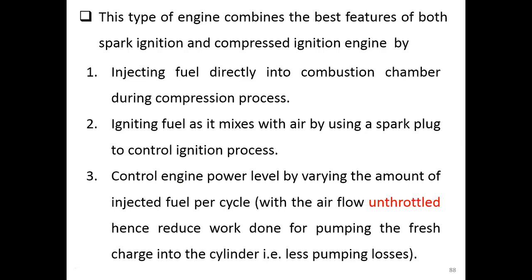So for this type of engine, our control is on the amount of the injected fuel only. We let the air flow unthrottled, so the air is free to flow into the engine. There is no restriction whatsoever, and that means we reduce the amount of work required by the engine.